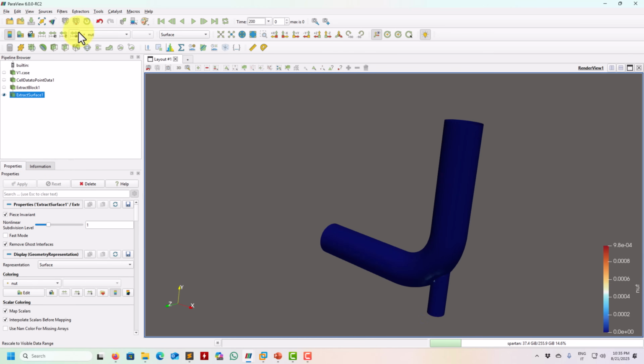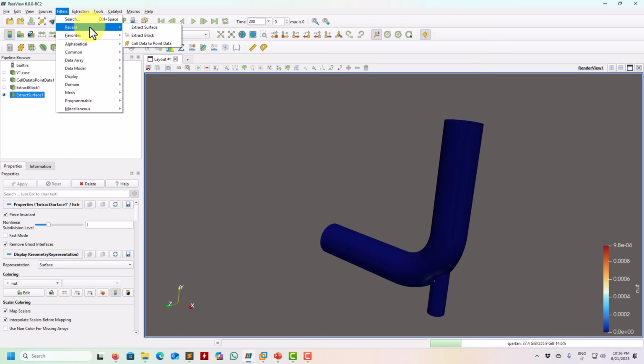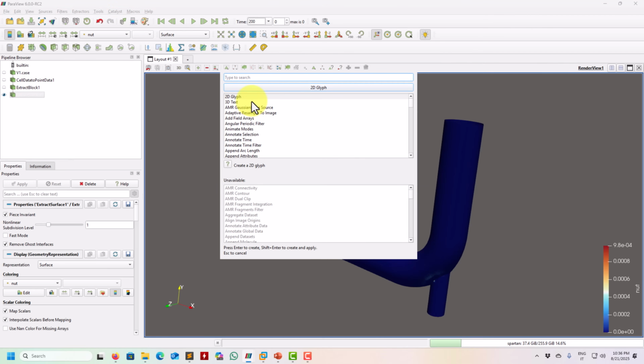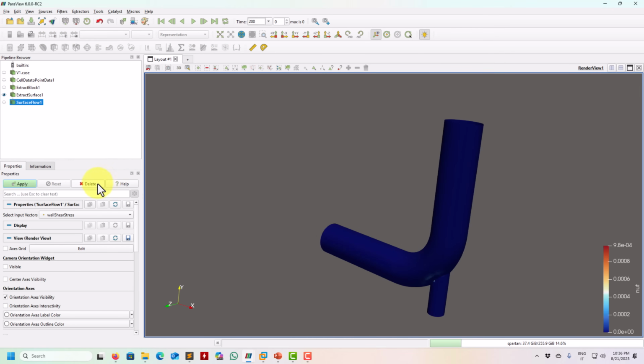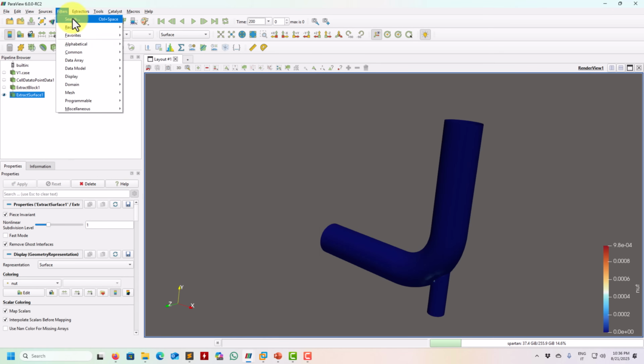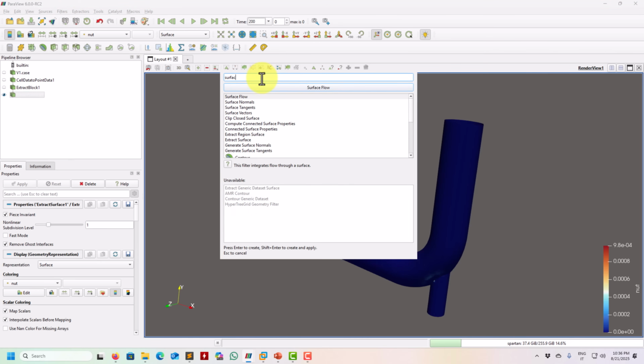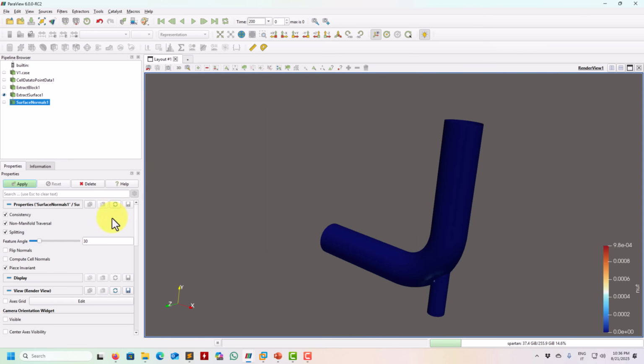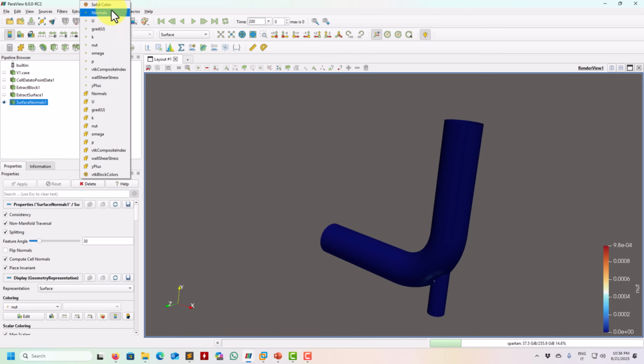You will have it in VTK. Now the filter will be Surface Normals here. So now we have surface normals. I want it also in cell centers. So at this point we have everything, normals in cell centers and points and all the other quantities.